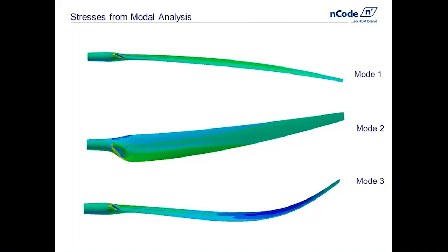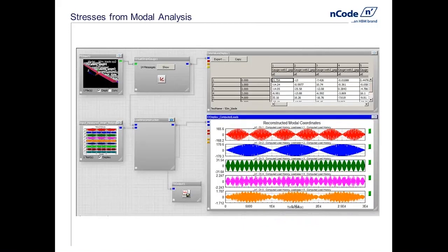And in the load reconstruction process, again, we have multiple gauges, and you'll see this in just a bit, along with the modal stresses. They go into the virtual strain gauge, and it outputs a matrix that's going to be every row being one of the modes that were computed for this structure, and every column being the responses from a gauge for those modes. And this is just piped into the scripting glyph.